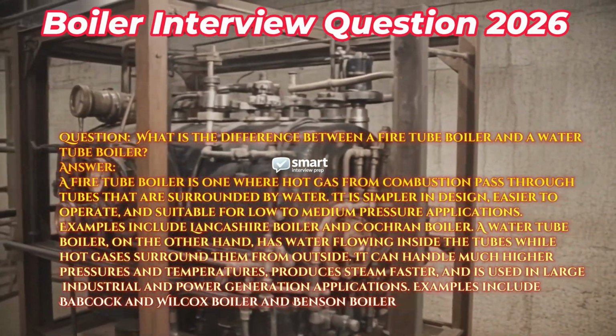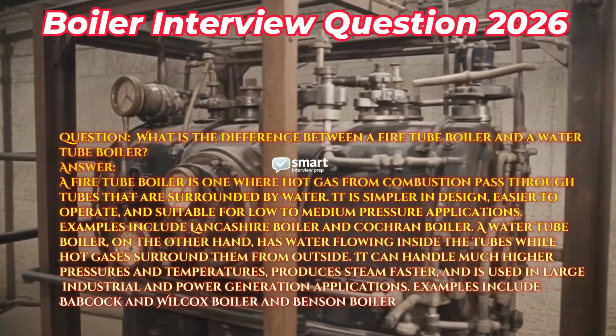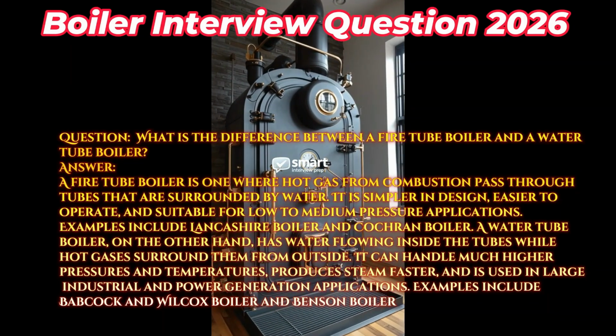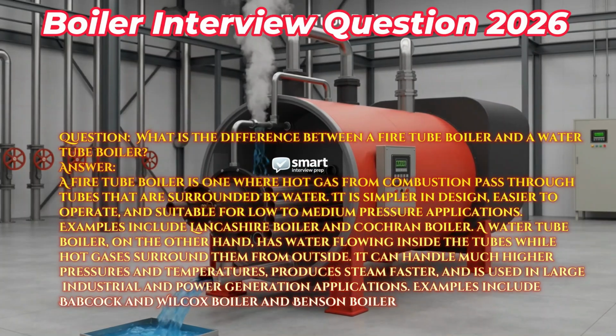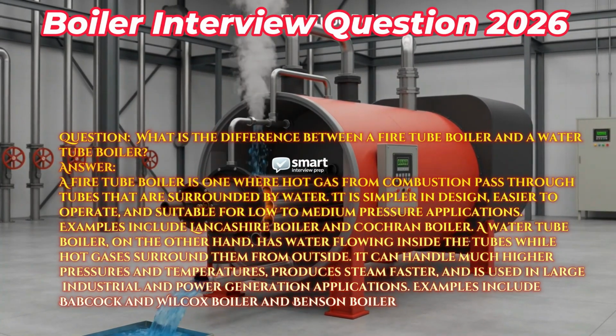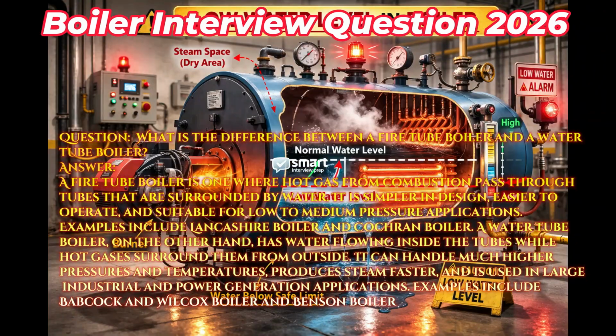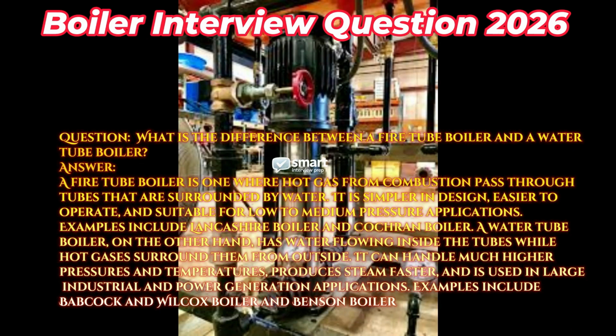A water tube boiler, on the other hand, has water flowing inside the tubes while hot gases surround them from outside. It can handle much higher pressures and temperatures, produces steam faster, and is used in large industrial and power generation applications. Examples include Babcock and Wilcox boiler and Benson boiler.